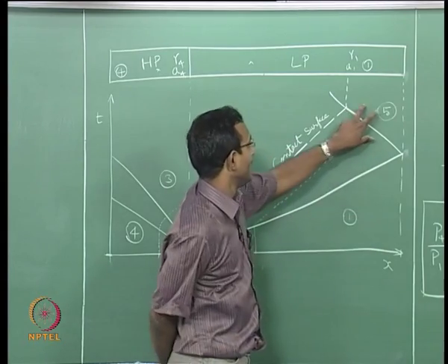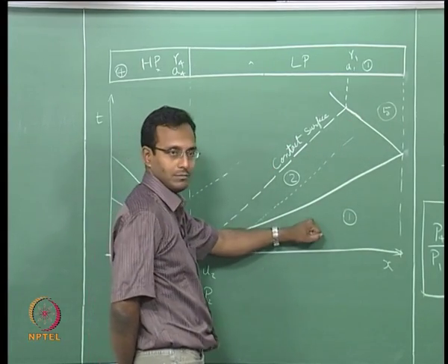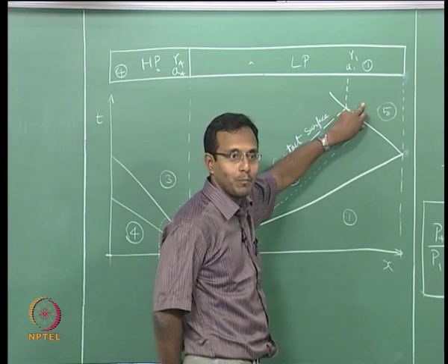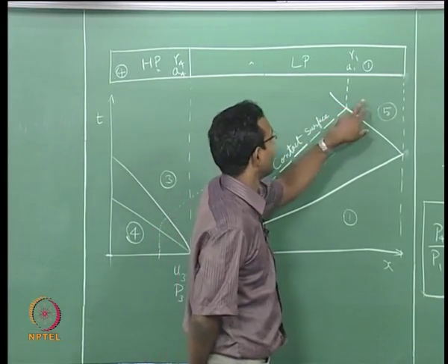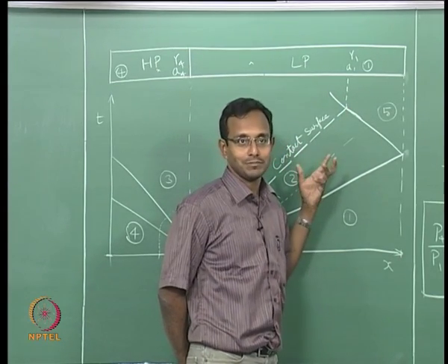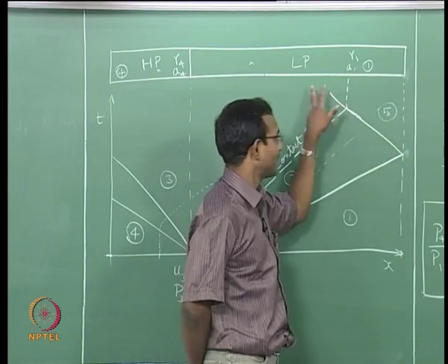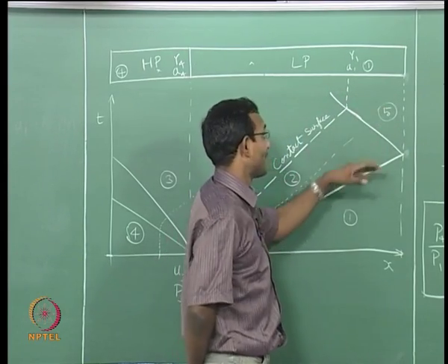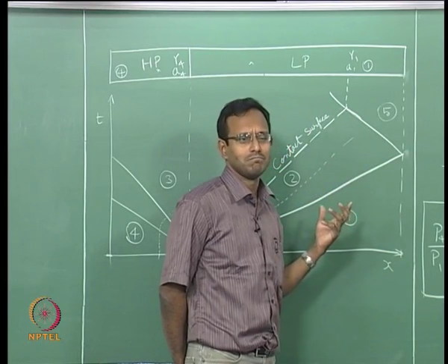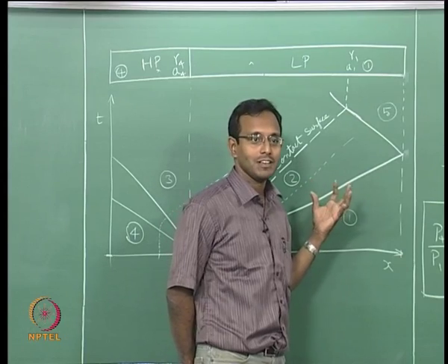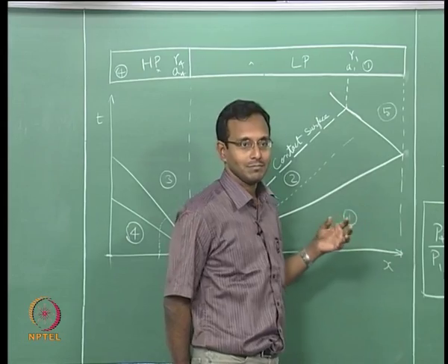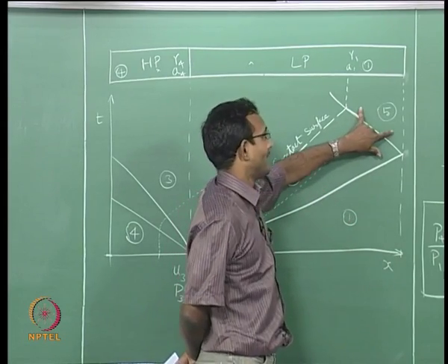So I have finally taken my gas at state 1 to state 5, just T5 P5, and now I can study suddenly pressurized gas at a very high pressure and temperature. Okay, it has been processed by 2 shocks, and all this is happening on a microseconds time scale. Within, say, 100, it depends on the length of the tube, of course. It could be anywhere in the order of 100 to 500 microseconds. Okay. So that kind of time scales.